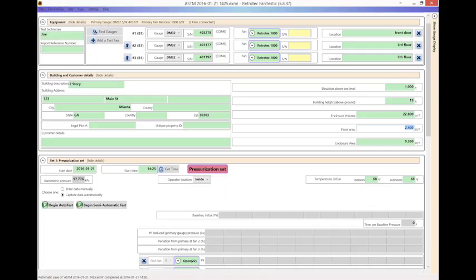If you put in none of those areas, it will give you a warning, and it will give you, let's say, equivalent leakage area or CFM at 50 or whatever that don't require any of those areas. So just because it's asking for those areas, you only put them in if you want results that use those areas. Great, thanks for that information.